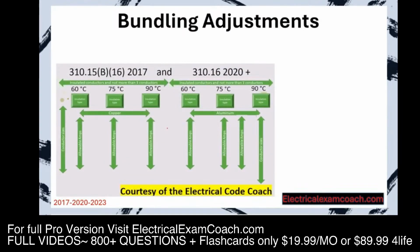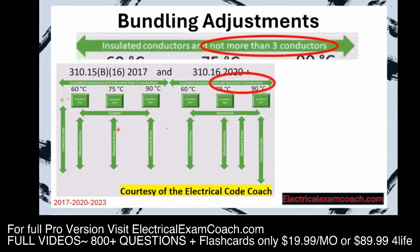And these values down below this table are true if, well, the question is if what? If you look at the paragraph above the table, the one that I said we would come back and look at later, it's got some parameters there. It says, hey, these are the ampacities of these conductors if, and the first if that we're going to look at is if there are not more than 3 current carrying conductors inside of a cable, pipe, or even buried in the earth together.